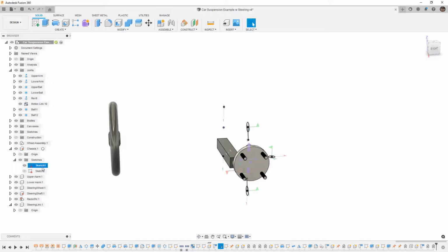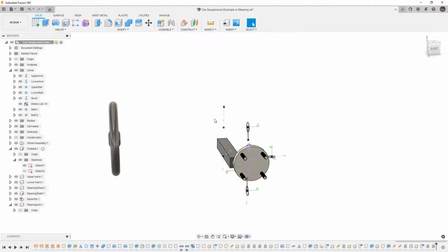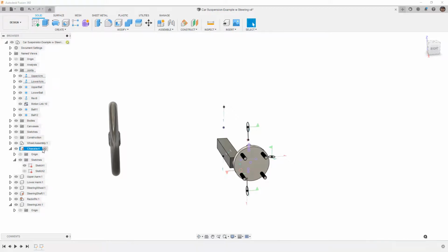This can be done a few different ways, and I'm just going to simply go in and edit this first sketch. And note that we put these points at a couple different locations, but they were done from the front plane. If we want to take this into an actual axis of rotation, assuming that it's going to be parallel with the center line of the vehicle, what I mean by that is if we create a sketch in our chassis, let's go ahead and activate the chassis.